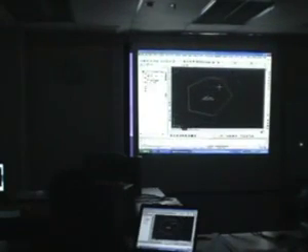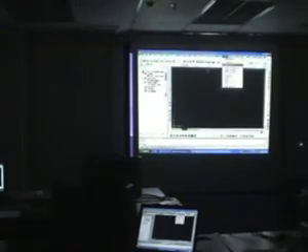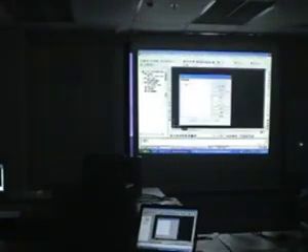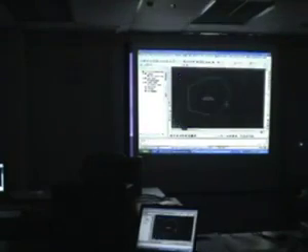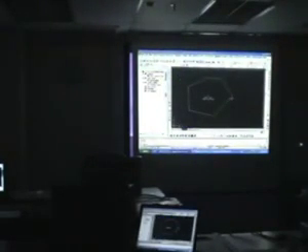And this is very unique also because they have a parcel manager, meaning if, let's say, this is gone, like, okay, I've lost the drawing or I accidentally erased it from the drawing, it doesn't mean all is lost. You can still call it back from the parcel manager. You can see parcel 1 is here. You just click import and it will appear again.